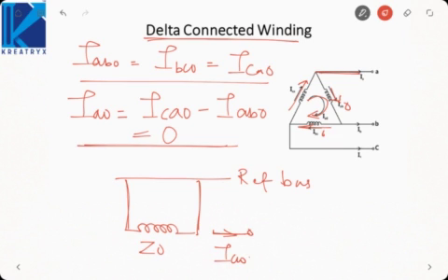That is, zero sequence current cannot enter the line, but it can keep on circulating in the phase. Though this circuit might not look practically correct to you, it is just a representation to indicate that zero sequence current can exist in the phase but not in the line. Okay. So that is how we draw the delta connected zero sequence network.